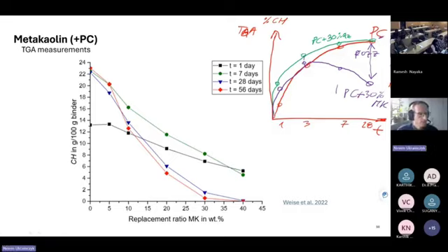But do they also react? Probably not so much pozzolanically. It's only the surface, a little bit of reaction. You need to mill it to have a high surface area to have a pozzolanic reaction of glass. If it's a fiber, then it's only a little bit on the surface. Yeah, no problem, you can add it. Yes, exactly. Any other questions?